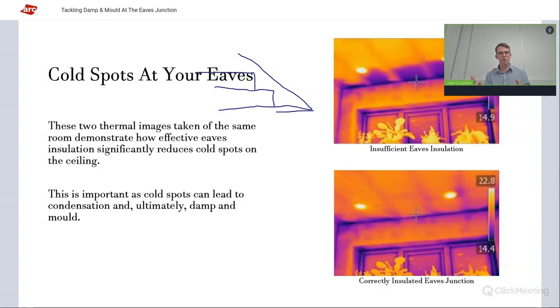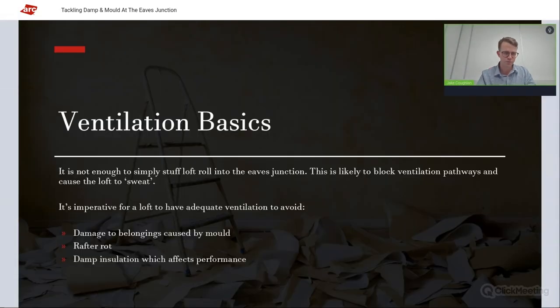But if you heat up all of those walls and ceilings, but then you've got a tiny strip of cold spot, like here, all of your moisture is going to condense on that one spot, and it's going to be dripping. It's going to be horrible. So that's why we can often see it gets worse post retrofit. So that's the thermal bridging elements to this.